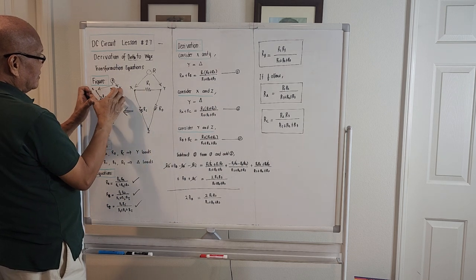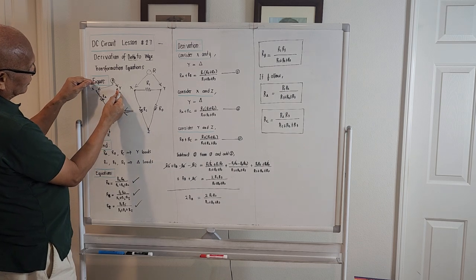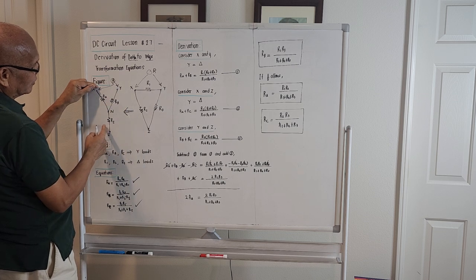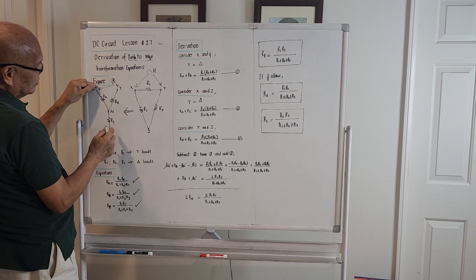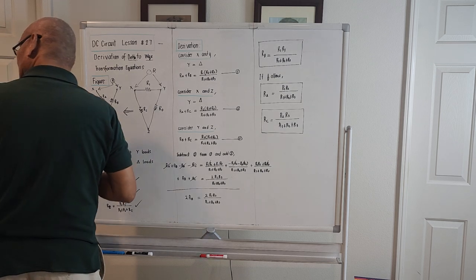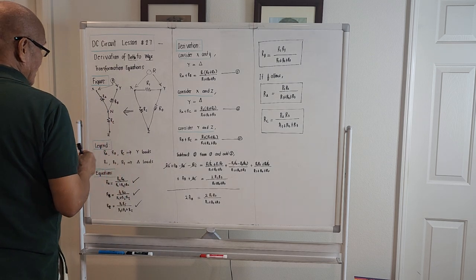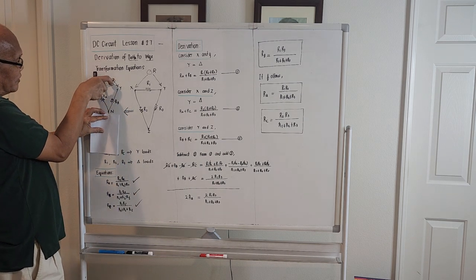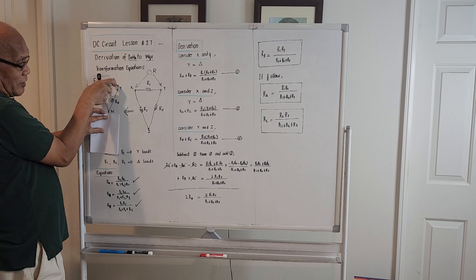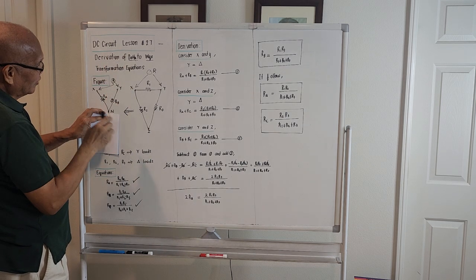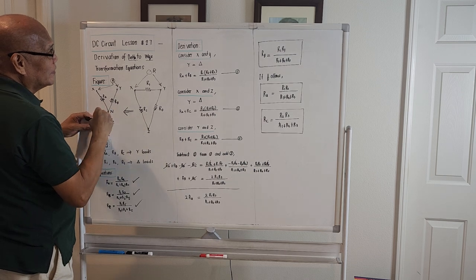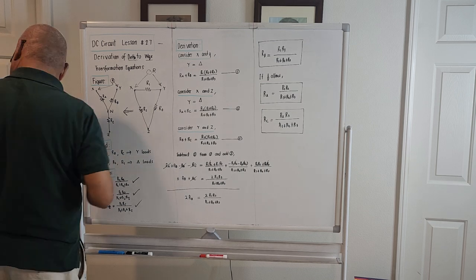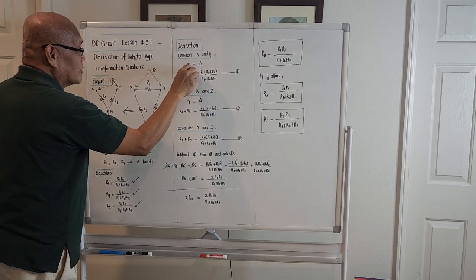If we are on the Y equivalent, if we try to put our tester here, okay, R sub C will not be included because it is an open circuit. So what will come out will just be simply... it seems R sub C is missing. If we try to tap the multi-tester here and we get the resistance, the reading will be the value RA plus RB. So this is RA plus RB.